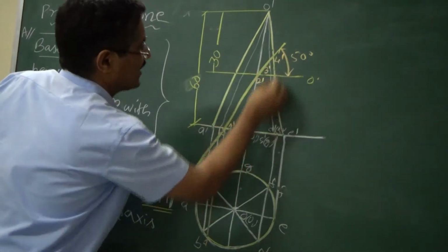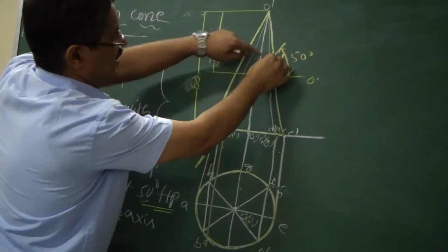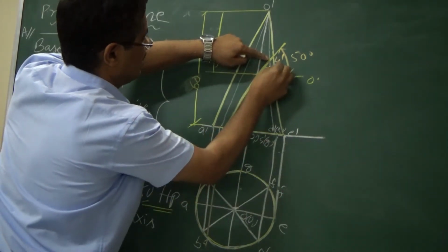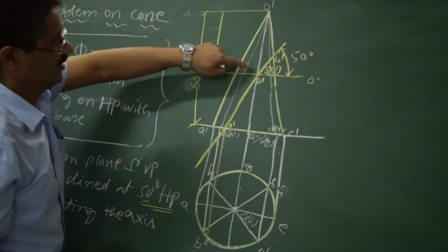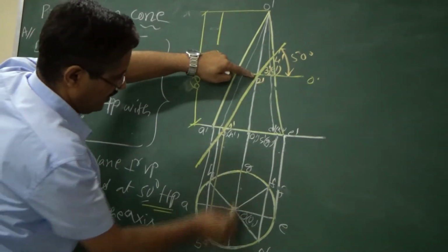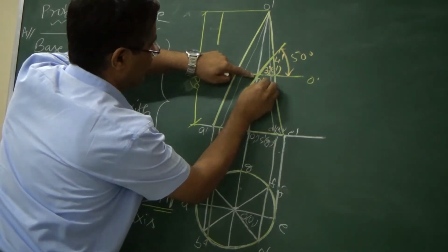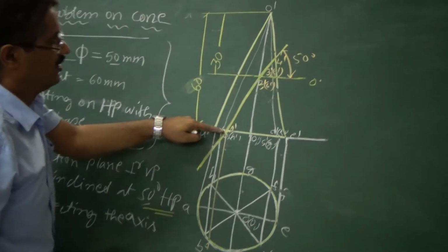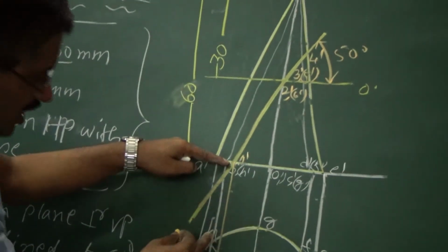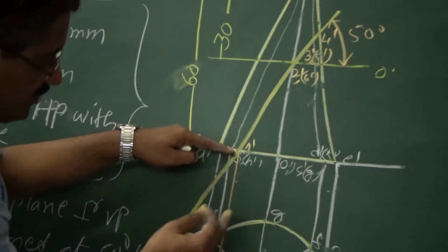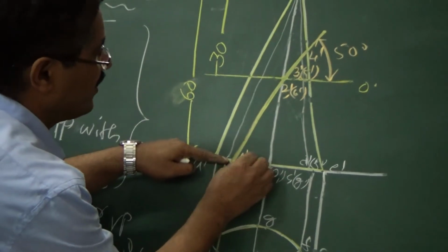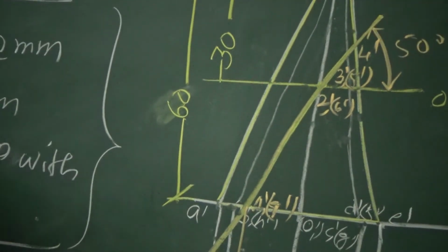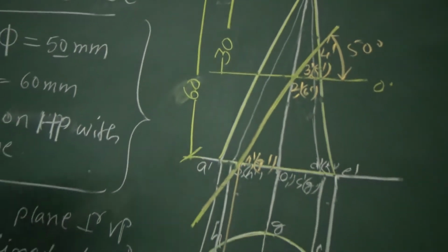So next reverse, when you move here, an invisible one, that is your point number F. So call this as 5 dash in the bracket. So move down here, again G was not marked, that is 6 dash in the bracket. So move down here, so it is cutting the base. So I have already told base cutting there will be 2 points. This will be now 7 in the bracket. So only 7 points that you get here.